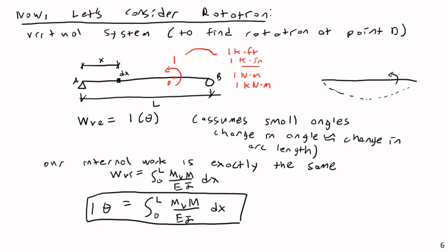Oh, yes. Can you repeat why we apply a couple at D? Okay, the question was, can we repeat why we apply a couple at D? Yes, because remember, the principle of virtual work fundamentally is that the external work done by the virtual force is equal to the internal work done by the virtual internal force. In other words, a virtual force moving through a real deformation is equal to a virtual internal force moving through the internal deformation. That's the fundamental principle. So we need to have some sort of virtual force that corresponds to the type of deformation we're looking at. In this particular instance, we're wanting to find a rotation.